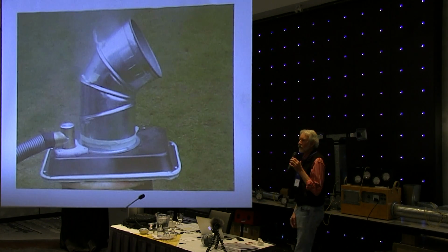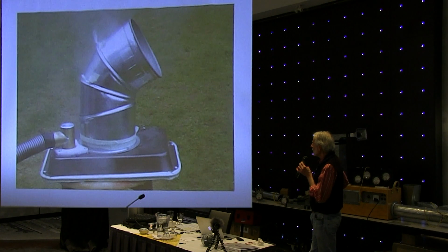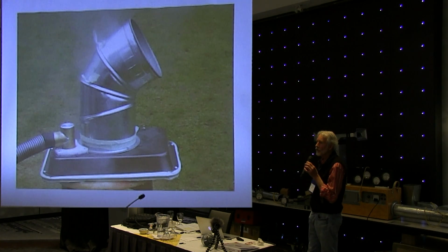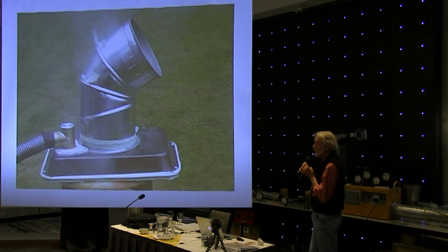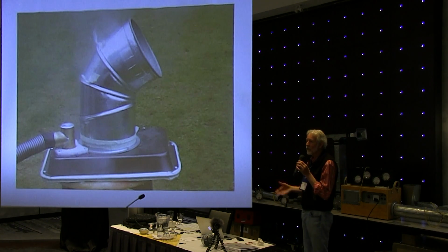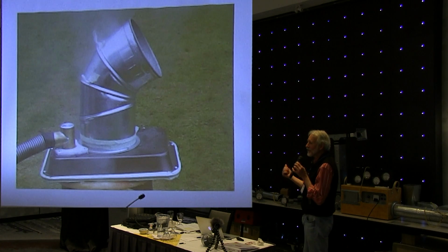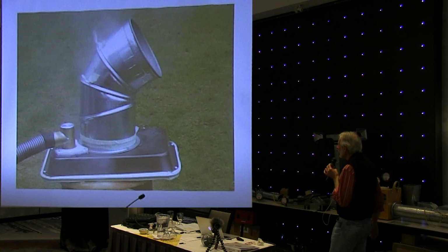I probably personally tested 200 houses using this, and when you get a leaky system, smoke descends all over the place. We had a few people panic and want to call the fire department. We used to use smoke bombs, and that did freak everyone out because you can't stop it once you start them. This thing's a lot easier to pull the plug if you get desperate.